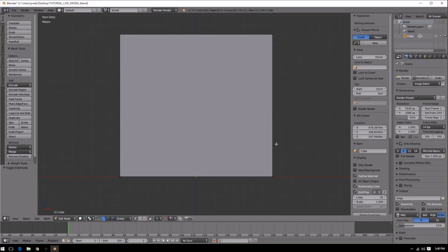So we're going to count up about 5 units so we kind of know where we want to make our first floor. And I'm going to hover over our mesh and hold Control and hit the R, as in Romeo, button. Once you do that, your loop cut tool is engaged, but you're going to notice it doesn't see anything. You have to move your mouse close to an edge. And when you move your mouse close to an edge, you're going to see that pink line show up, and that means that the loop cut tool is engaged. And you basically want to move it so that you can make a horizontal cut or a vertical cut. And once you figure out what you want to do, you click it.